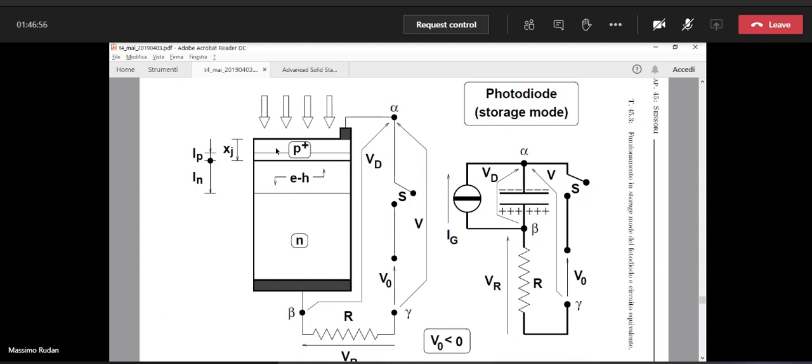So we had an absorption in the initial region of the semiconductor, and this absorption is lost. How long is the initial piece of the semiconductor? It is equal to the neutral region of the p-type, whose length, as you can see from the symbol, is xj, the junction depth, minus Lp.